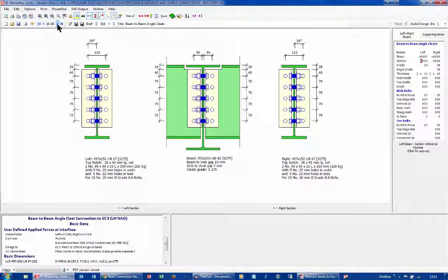Now, the Eurocode, the SCI Green Book does not cover angle cleats because it feels that they're out of date and old-fashioned. But I know quite a few large fabricators that still like the angle cleats because they do not require welding. They are very quick and efficient to produce. So we have introduced, using the rules, angle design as well for you.